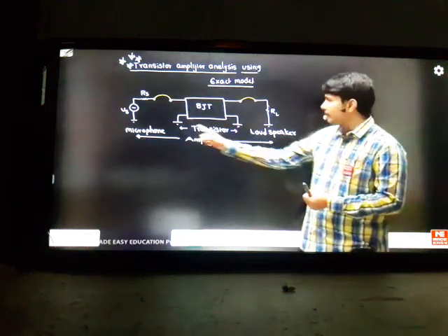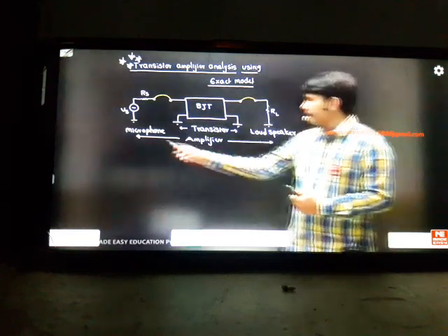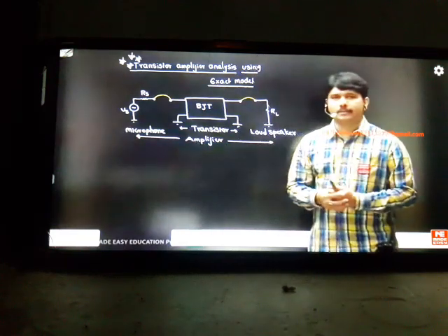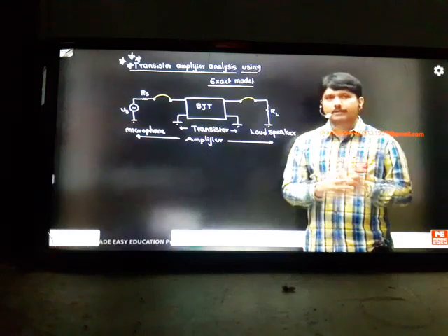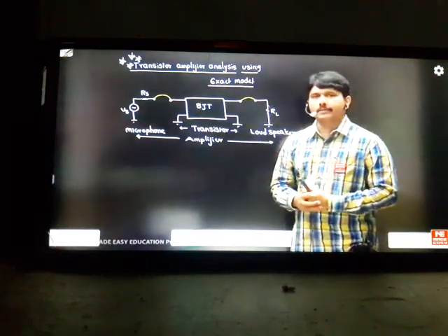Again, suppose I'm asking you, then you have to teach only up to here. That's why today in class I have to distinguish that transistor characteristics will be different. And from here to here, my gains, input impedances and output impedances will naturally be different. From the source, the impedances are different; if you talk from here, the impedance is different. So that is the difference between transistor and amplifier characteristics.